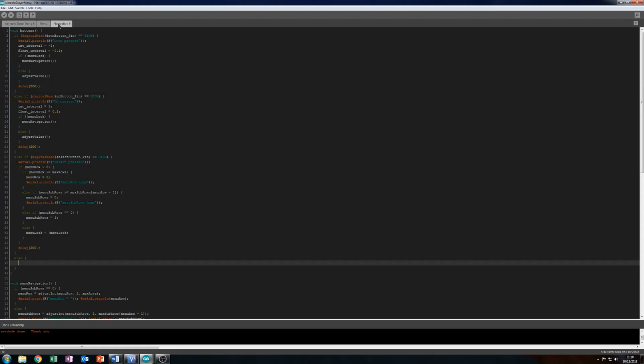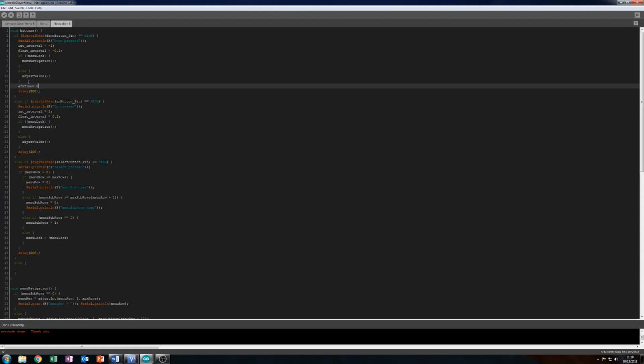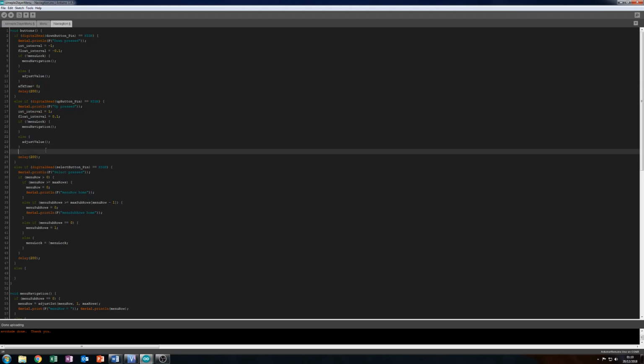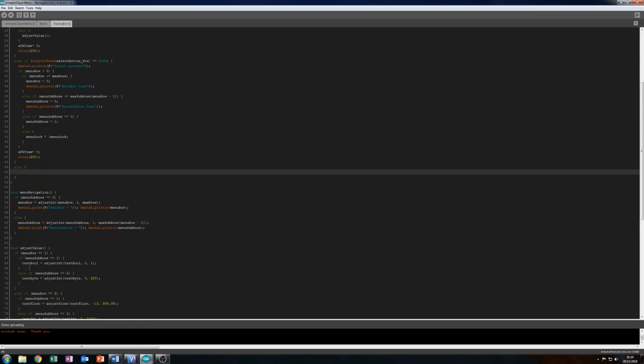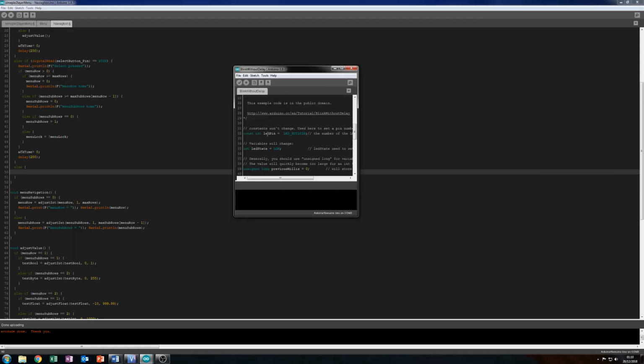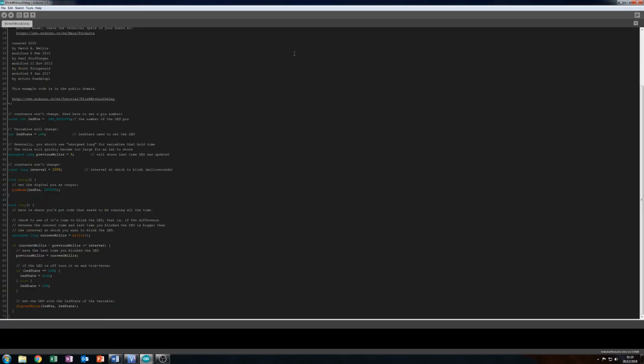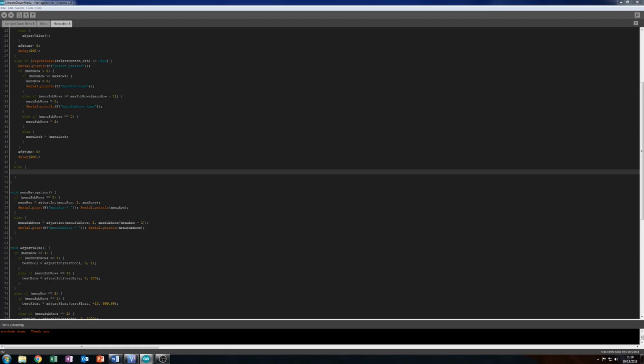Essentially, all you need to do is say, if you press this, set it to 0. Yeah, I'm sure you can already see where I'm going with this. So if you press any of the buttons, set it to 0. Else, here you want to use a timer, which you can get from, for instance, blink without delay. So I'll just show you that very quickly. I don't want to waste your time. We'll just pillage a lot of this very quickly. I'll put up some other screen, I'll show you how quick we can do this.